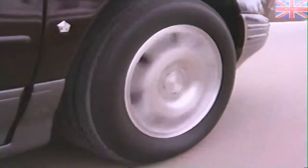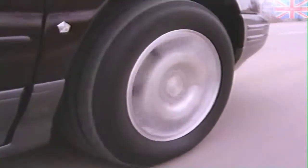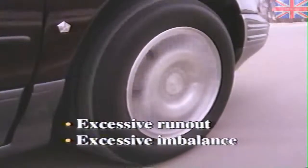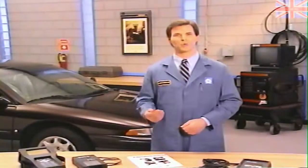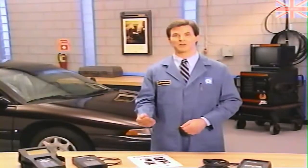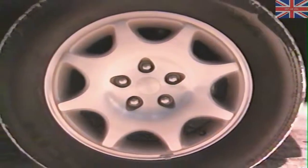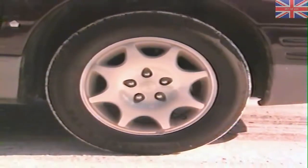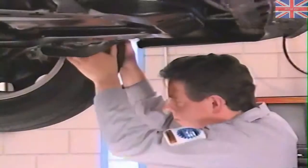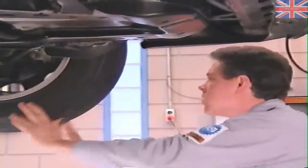We know that tire wheel vibrations are usually the result of one of two conditions: excessive runout or excessive imbalance. These conditions must be eliminated as possible causes. Because the runout of a tire wheel assembly directly affects the amount of imbalance, it should be corrected first. It's important to drive the vehicle before checking runout because flat spots may exist where the tires were resting on the ground. To get an indication of how much runout exists, we'll perform an on-car inspection.